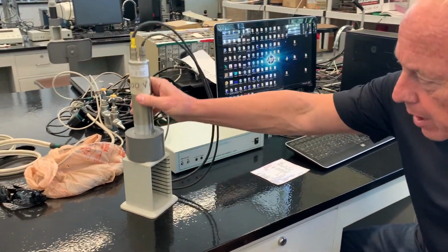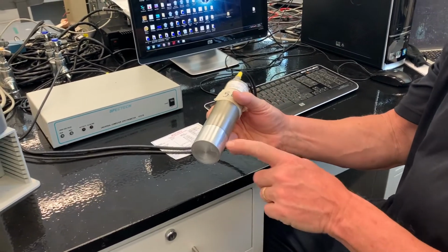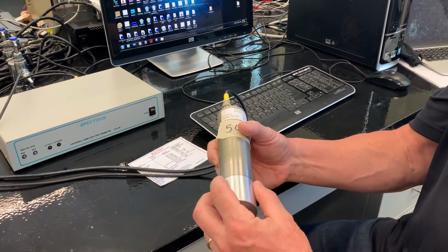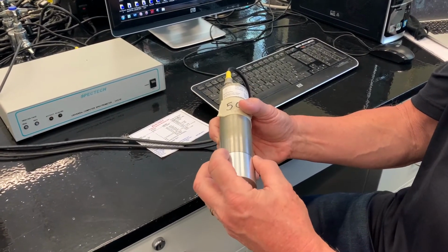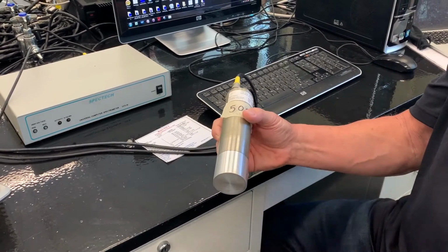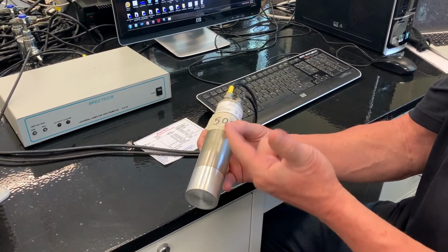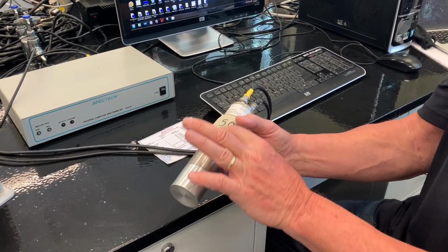So this is the sodium iodide crystal. You don't see it, it's transparent. It's housed inside of this aluminum shield, and the purpose of the aluminum is to first protect the crystal, but also to make it dark. We don't want any visible light from the room getting into the transparent crystal, because it will then get detected by the photomultiplier tube, which is over here.